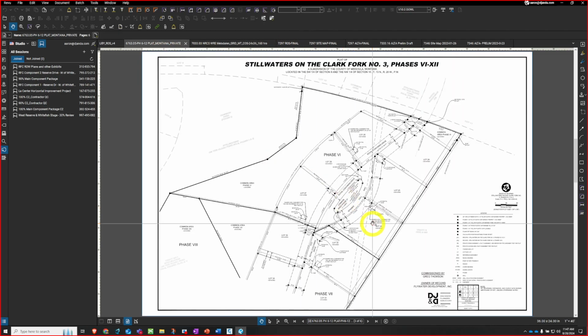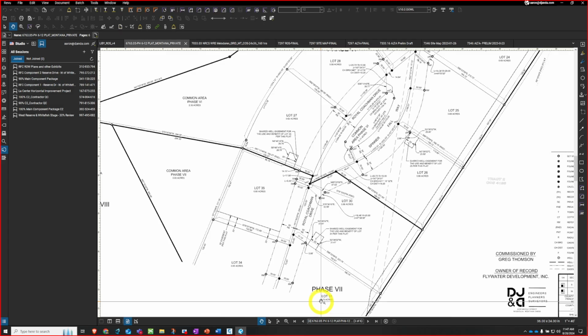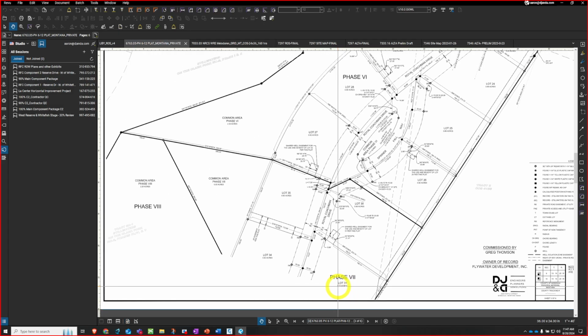This survey had a lot more overlap spots, so I had to use annotative objects. Annotative objects are nice in that they'll scale up depending on the scale of the viewport. You can also move them to one location for 20 scale and a different location for 40 scale. That's some of the power of them.